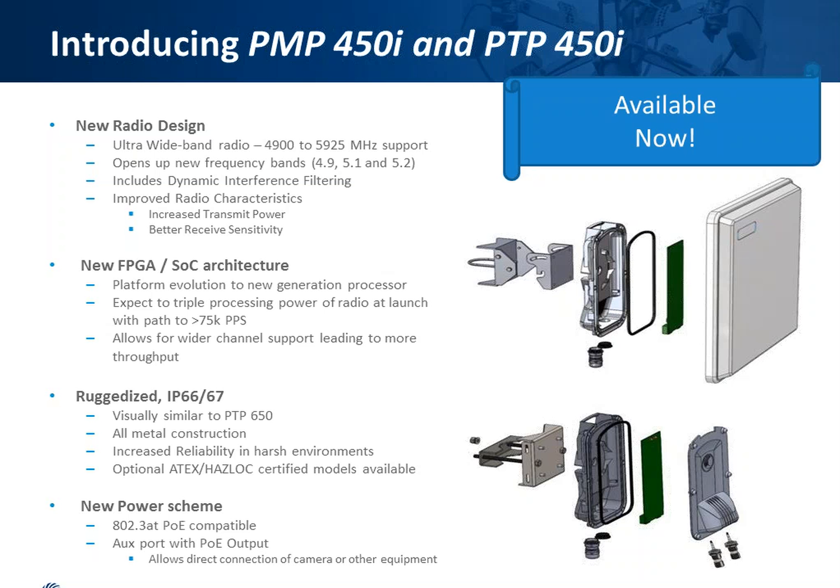It comes in a couple of different mechanical variations. One is an integrated access point with that 14 by 14 panel that you see on top. It's a 90-degree sector. It also comes in an integrated subscriber module that's a 23 dBi panel. And this is, again, in the wideband 5 gigahertz. It's ideally suited for industrial comms, but it also provides a step forward in the access point architecture.